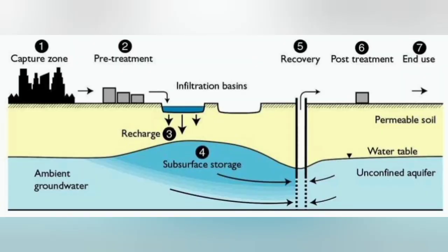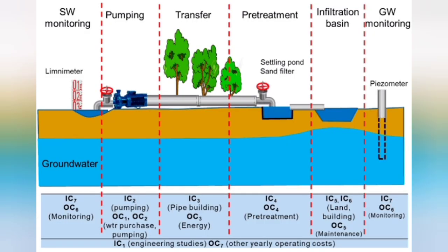As water infiltrates soil under natural conditions, the displacement of air is not complete even after many hours. Air spaces in the soil and the intermediate zone interfere with infiltration, as air is not pushed out by the infiltrating water but is gradually absorbed by the water. Due to this phenomenon, the infiltration rate may start rising towards a new high after a few days of continuous application of water.